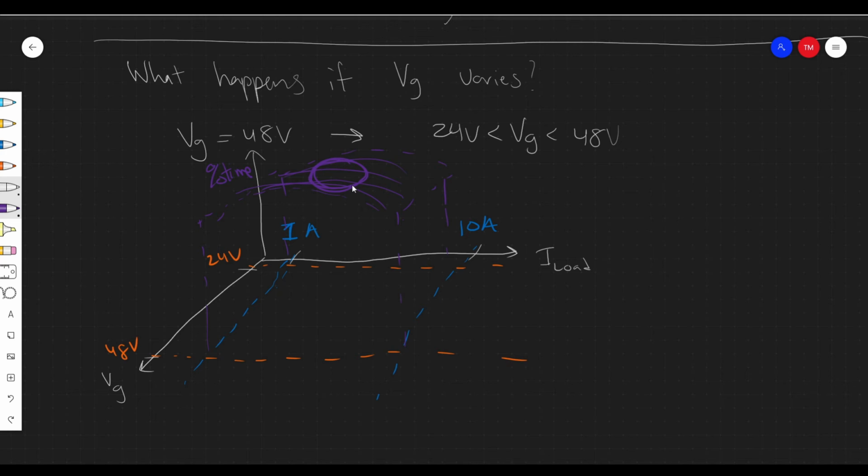However, one important thing to think about is the fact that the total charge, or the output capacitor design, is going to vary because we don't have this special case where N is going to be Vout over Vg. Now, because Vg varies and N doesn't vary, there's going to be cases where the current shape is going to look different depending on the voltage and current.